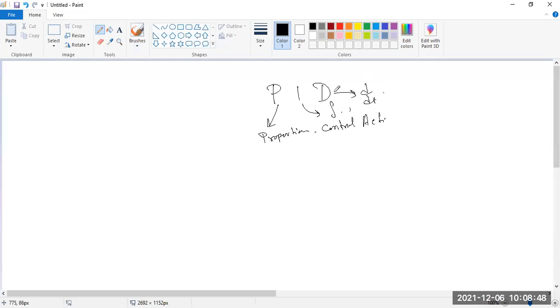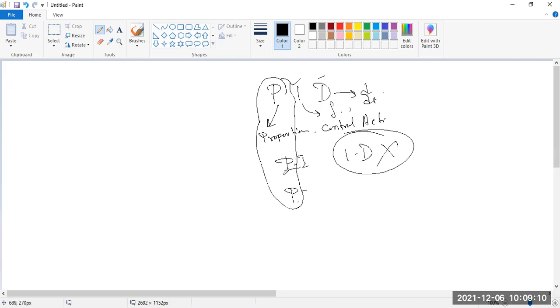Okay. Sometimes P and I control action is used. Sometimes only P action is used, but you never get a controller without P. You never hear of an I and D controller. No, it does not exist, because P is the basic part. Then we can apply I or D. But in practice, in industry, what happens? D is one type of braking. So the constant of D is always kept at a minimum.